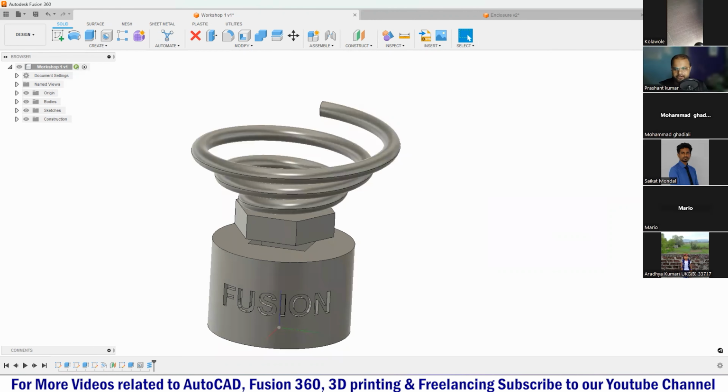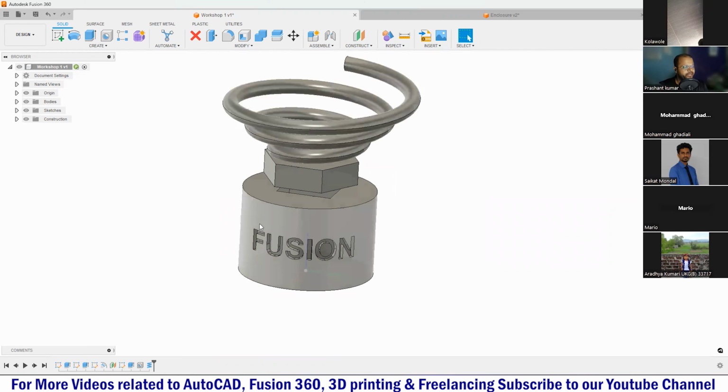Now the next agenda was how to export your 3D models for 3D printing. That's really important, guys. To export your 3D model for 3D printing, basically, because 3D printing is a process you can use to create a real object of your 3D model, it must be solid, right? So first, you have to make sure that once you expand your bodies folder, you are able to see this cylindrical icon, which shows that whatever objects you created are completely solid.